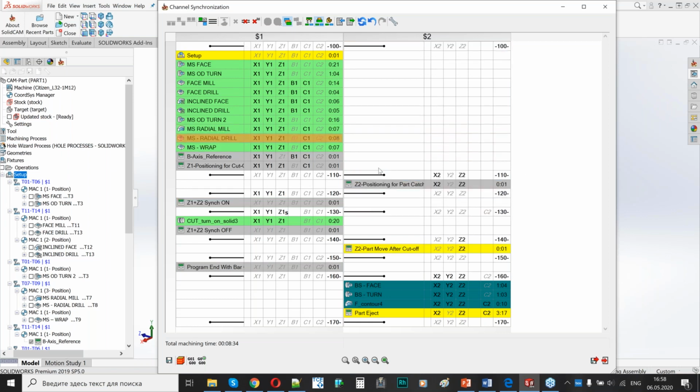What should be done next? Usually on the machine, or when you have your first project, you don't know if tool mounting on the machine was okay, if the tool setup table was okay, or if the part will have its dimensions as you have it on a drawing.